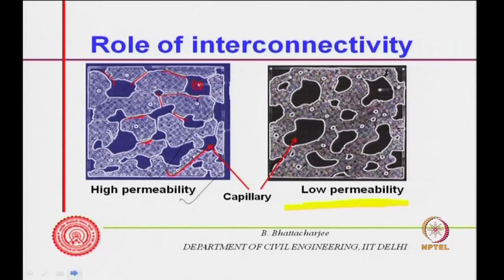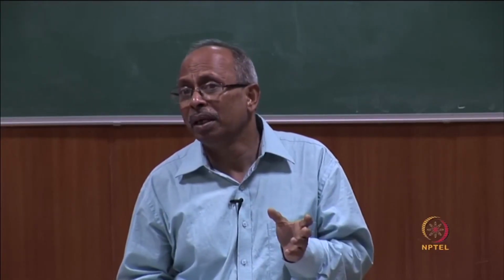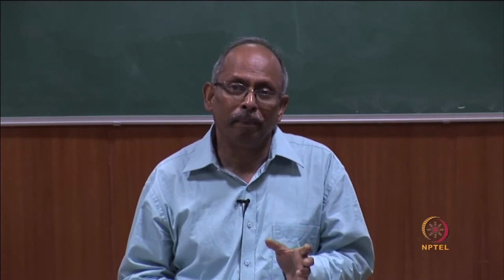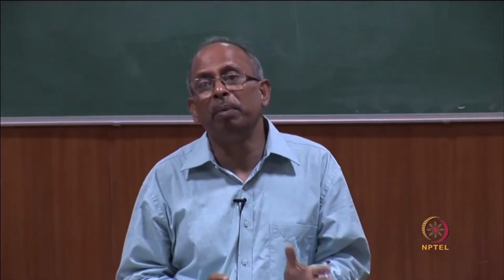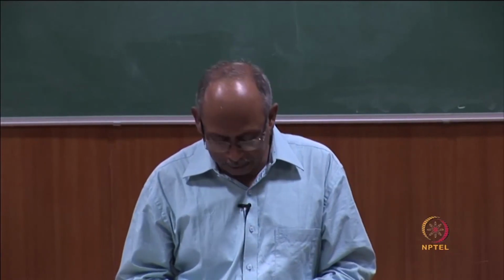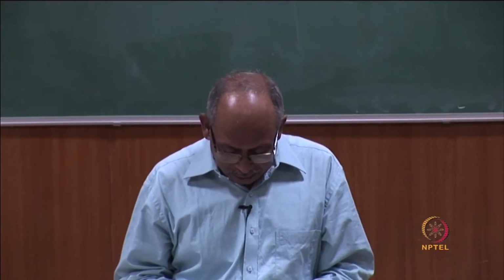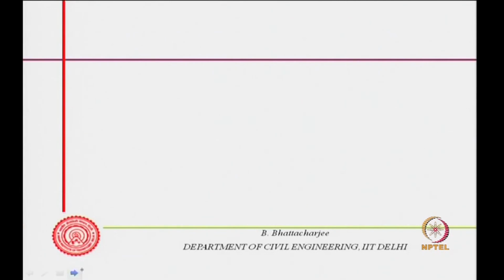Therefore, curing must also play a role, because if you do not do the curing, capillaries will not be segmented. I mentioned this when we were talking of curing. Capillaries will not be segmented if we do not do the minimum curing, which is related to capillary segmentation. So, this gives us certain understanding related to permeability.